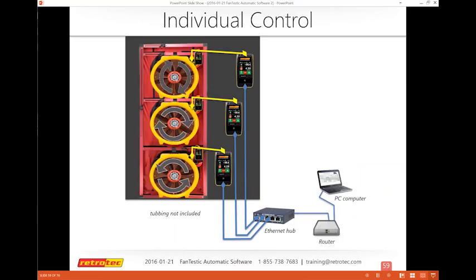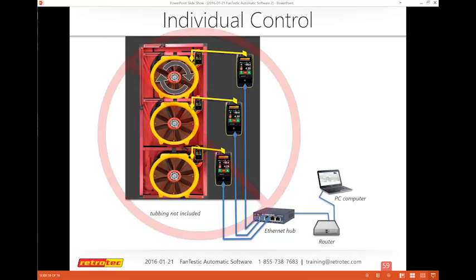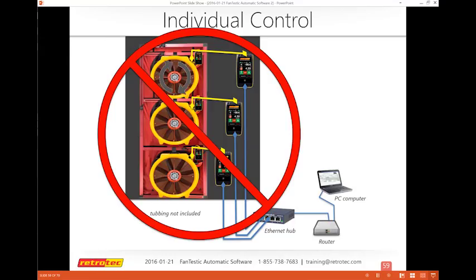Sometimes it's not apparent when you have these three fans stacked, but you may have three fans here, and you may have another hallway that's 10 feet away. Then the fans are actually in this common zone, and they're fighting each other. So that's why common control is a much better way to set these up so the fans are not fighting each other. And again, I can do this in the computer with my selections, or I can wire them in a way that allows them to do that. So this would not be the way to set that up.